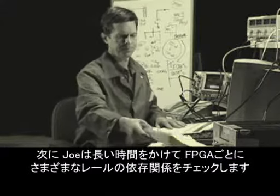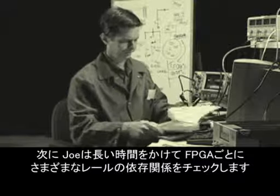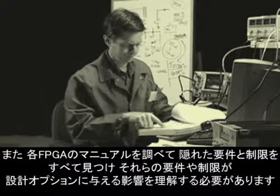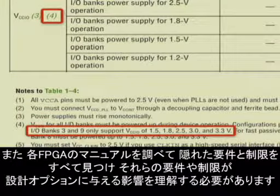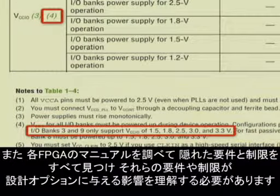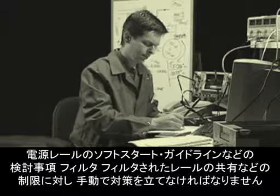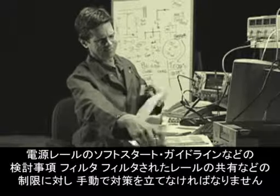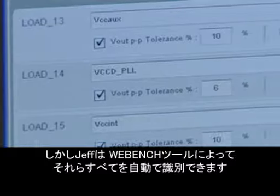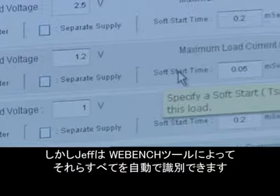Now Joe takes quite a while to check the various rail dependencies for each FPGA. Joe needs to carefully examine the notes in each FPGA manual and make sure he finds all of the hidden requirements and limitations and understand how they affect his design options. Joe has to manually figure for considerations like power rail soft start guidelines, filters, and other restrictions such as sharing any filtered rails. Jeff has all of that automatically identified for him and presented to him in the WEBENCH tool.